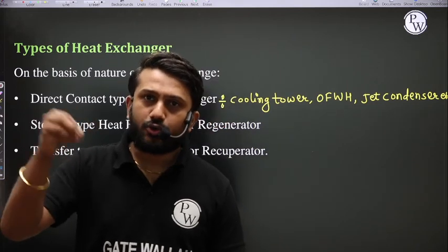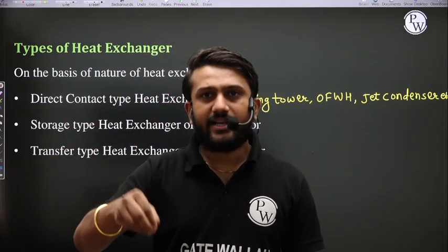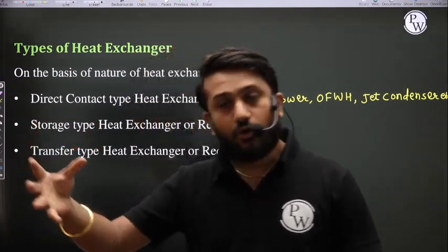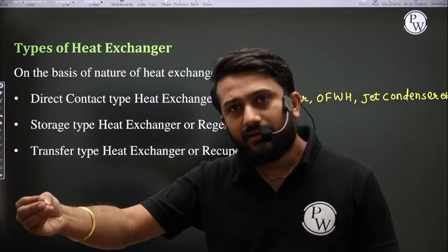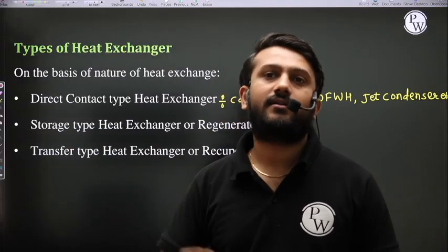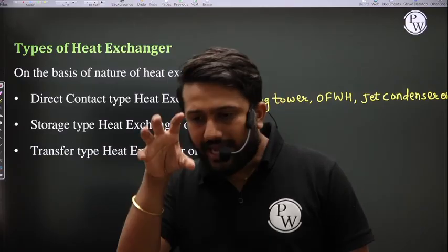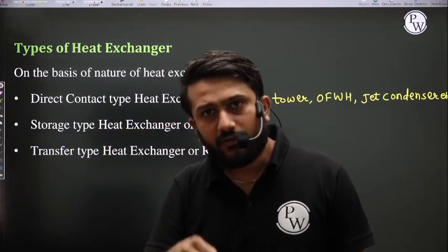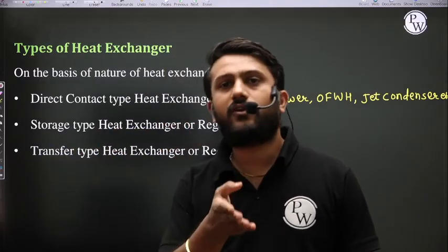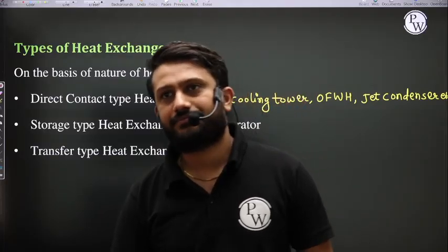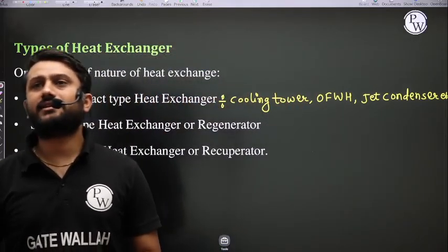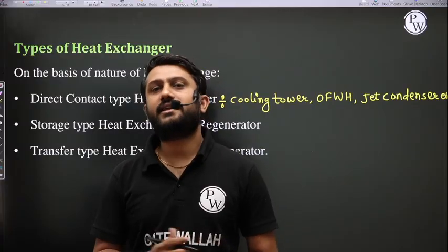That medium stores the energy, okay? Which energy? The energy it takes from the hot fluid, right? So that medium takes the heat energy from the hot fluid, stores it, and when the cold fluid passes through it, it gives it. Is it fine? So that is known as the storage type of heat exchanger or regenerator, right?